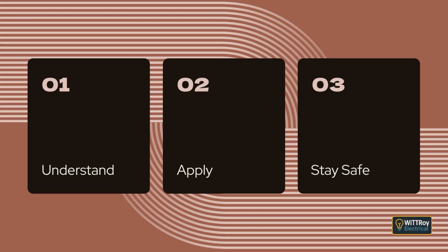There is an exception for some underground distribution systems that use special cable cabinets instead of a normal switchboard. A main switchboard must be provided for each electrical installation. This board holds the main switch, protective devices, and control equipment. Clause 2.9.2, Location of switchboards.